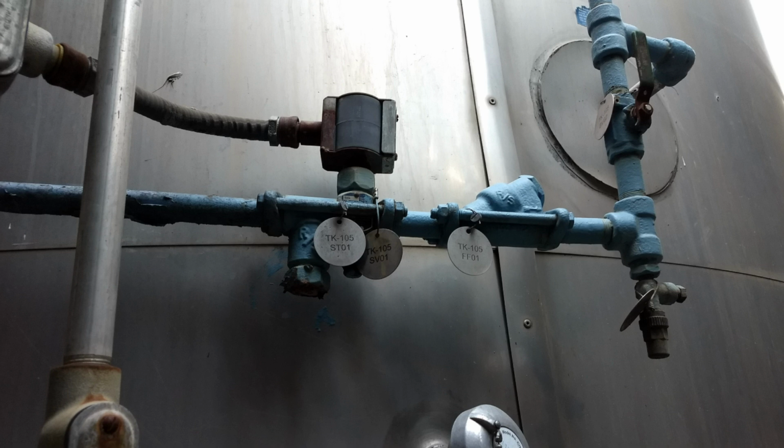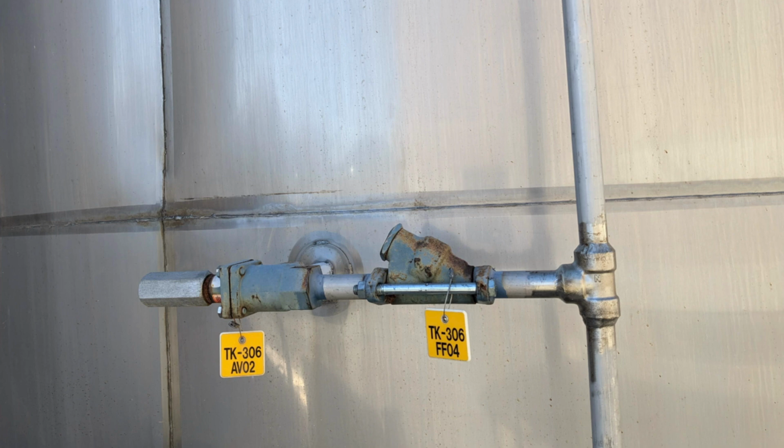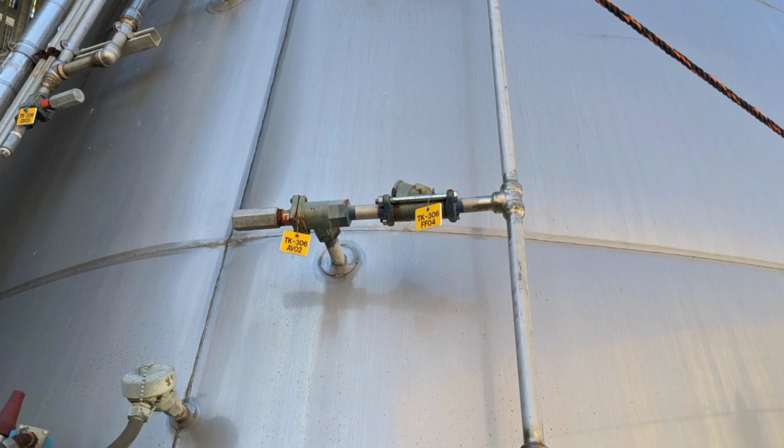The orifice expansion device is commonly found in smaller, low-cost systems due to its simplicity and reliability. The downside of orifice expansion devices is that they cannot adjust to changing load conditions, and they are susceptible to clogging, which can be mitigated by installing a strainer upstream of the device.